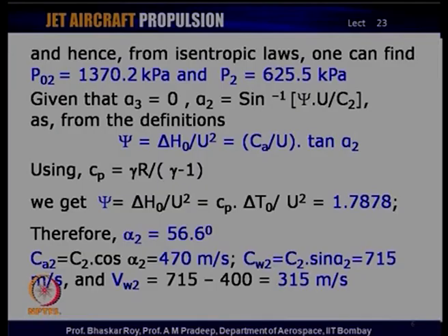Higher this number is, higher the stage is being asked to perform. And so, keeping an eye on this number tells you whether the stage has been sufficiently loaded or the stage loading has been maximized. And in case of aircraft gas turbine engines, as we have discussed before, we would like to maximize this number without causing undue gas dynamic or structural problems.